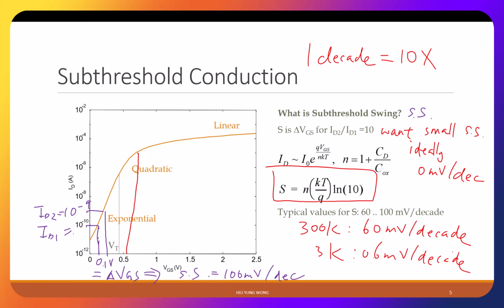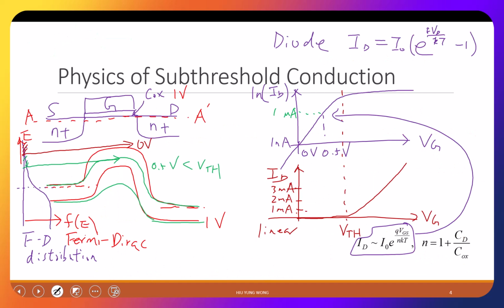It is like this. I have a transistor here, and then here I have the oxide. This is the oxide, and this is the gate. So when we talk about subthreshold slope, we're saying that if I can reduce the barrier by 60 millivolt, then I would have 10x more current that can go through. But as we said, this is not a diode.